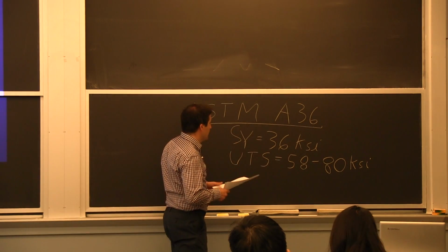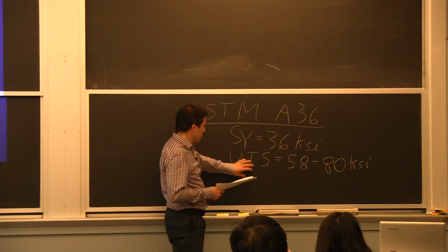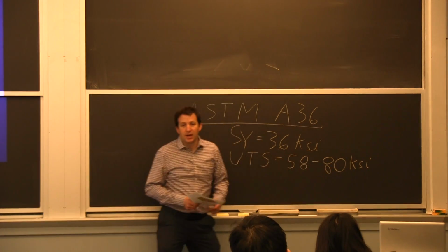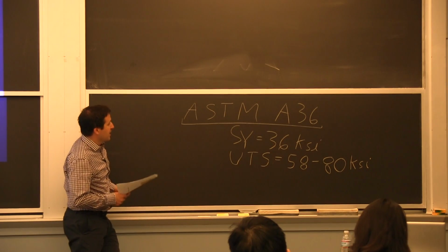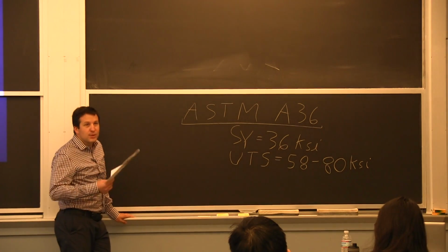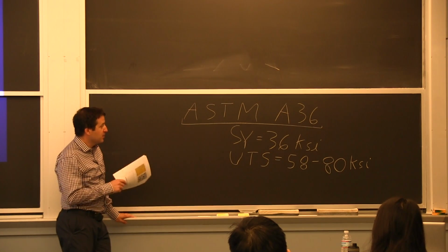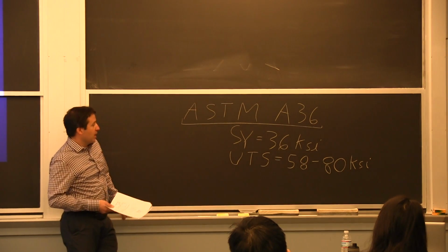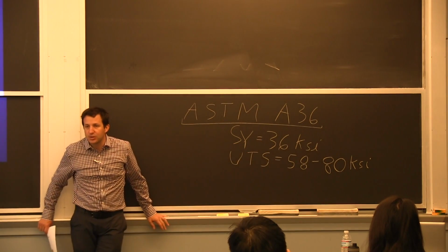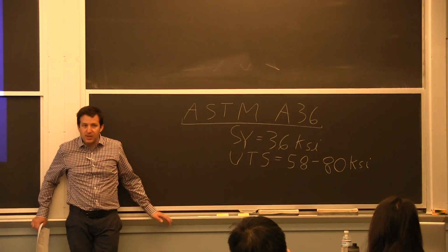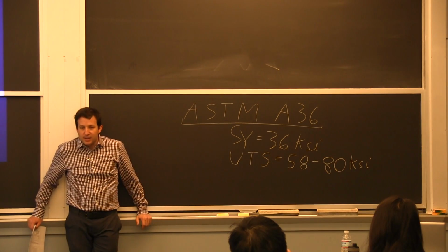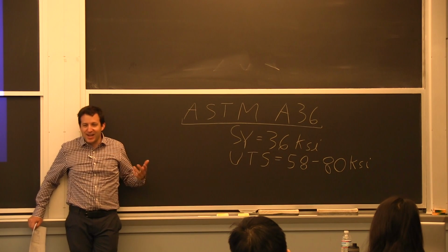The structural steel one doesn't. All it says is that when you run your tensile strength, you shouldn't be above 80. But if we were to take a piece of a beam from a lot of construction sites around here, I bet you we will be in the 40s, maybe even the upper 40s, with respect to the initial yield strength. And it's perfectly acceptable with respect to the specification, but it's not exactly defined.